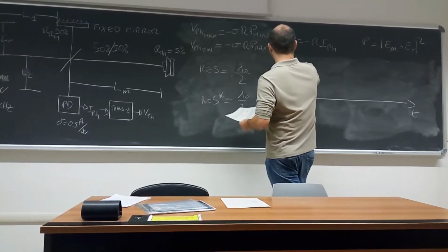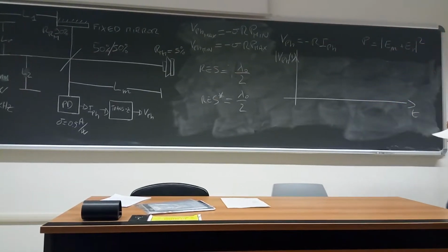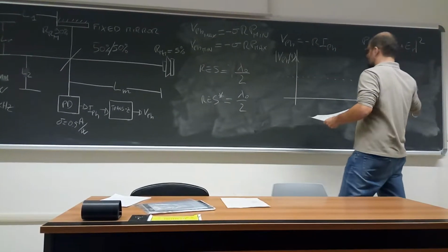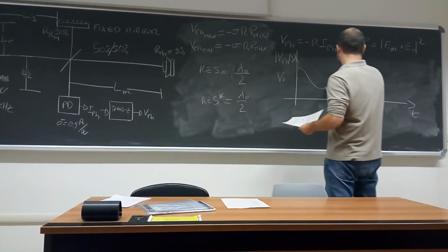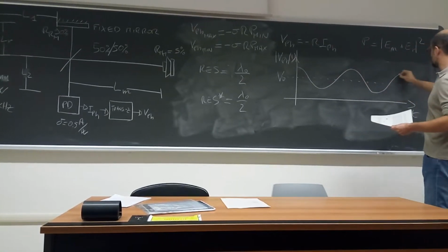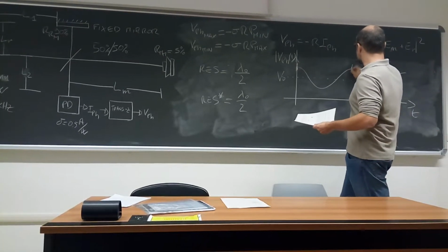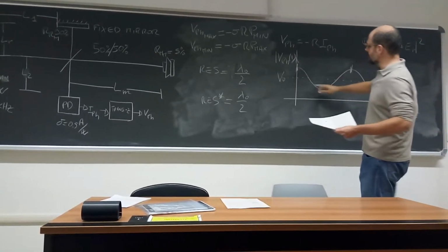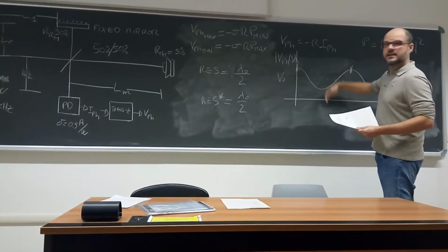Let's say this is the modulus of the photodetected voltage, so whatever the configuration of the transimpedance amplifier, the signal is always the same, and you have, let's call it, the mean value. In this condition, okay, so you can count just fringes, obtaining one count for each period, or you can say, okay, I transform this signal into a squared wave, then I do the derivative, and then I can always count also for the minus jump.